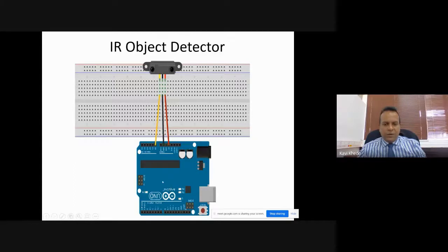This is an Arduino. You're familiar with this. So this is analog. It is giving analog data. It is capturing something, and this is being fed to my microcontroller on the port A0. Then in my program, I need to write how I read this A0. The value that is being sent by the sensor will be read from this port here. This is again just to introduce you. We'll do this in our next lab. We are starting to build such circuits to read from a sensor and to transmit to an actuator. So these are two things that we are going to start to do, and to start writing our Arduino program.